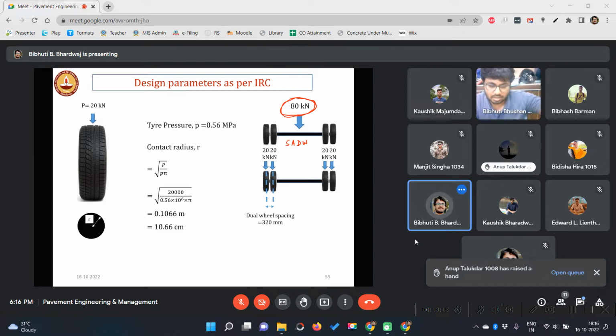So all these loads have been already converted to these axles by multiplying with the VDF. So now if I say 40 MSA, in our case it's 84 MSA, that means 84 million axles of this category are passing through the road or will pass through the road during its entire design life. So we don't have to consider other axle types, only this one is sufficient.